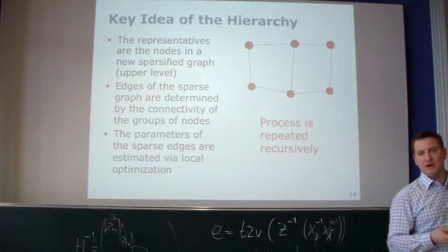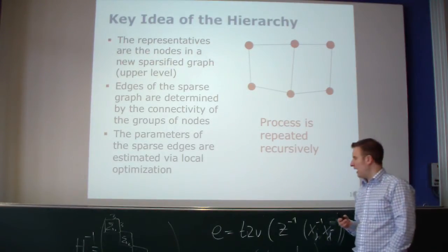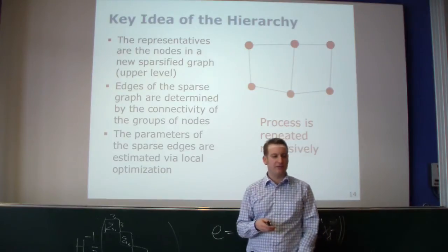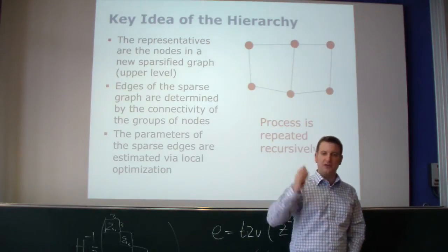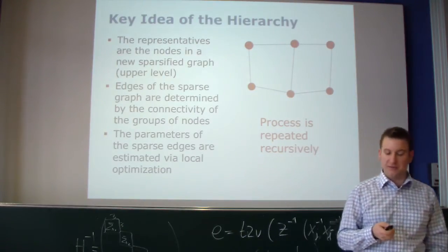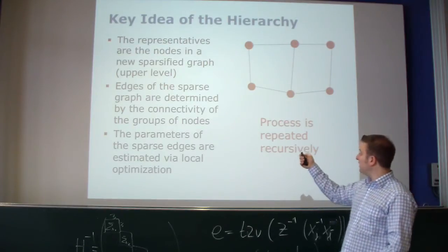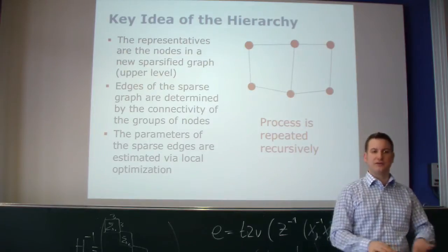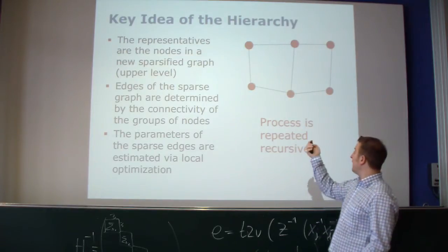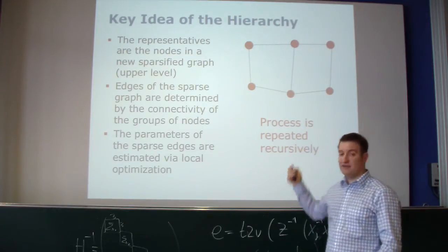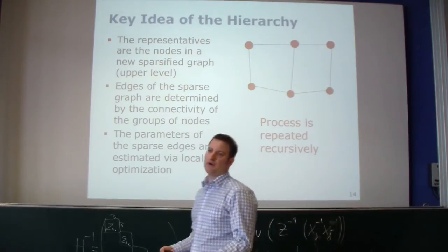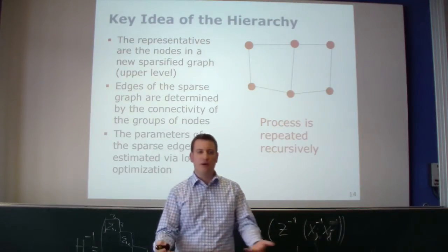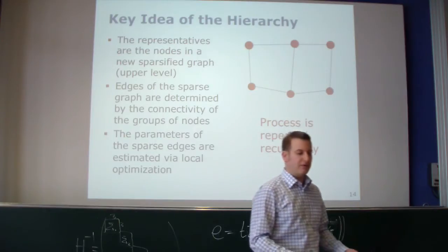We haven't said anything about how the optimization is done. So consider this is our highest level, and we now want to do the optimization. We've said we have those edges, and these edges represent or approximate all the structure on the lower levels. So if I optimize these nodes over here with these edges over here, I also get an approximate solution for the configuration of the pose graph on the lower level.